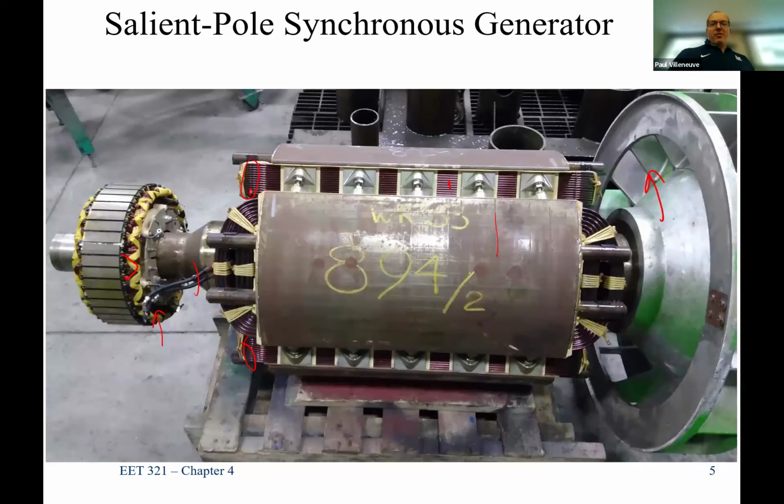Anybody know what the tape is for? Or it could not be tape, it could be like a cloth. Keep the line straight. Yeah, basically keep them in position, because most likely you may have some spacers or separators in here, depending on the voltage, that keeps it from moving. And if you have this thing spinning along, you don't want those windings moving relative to each other.